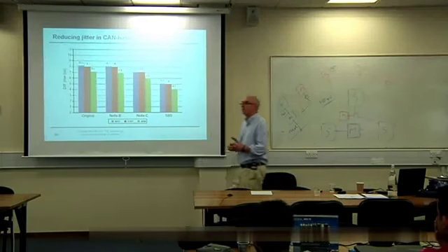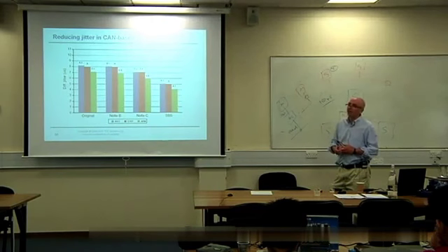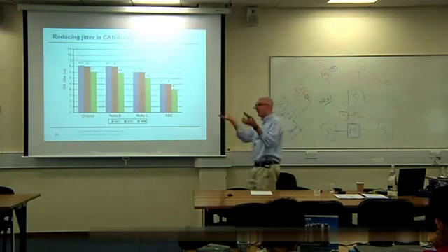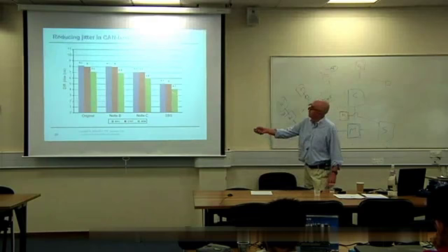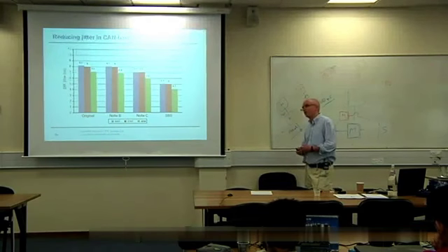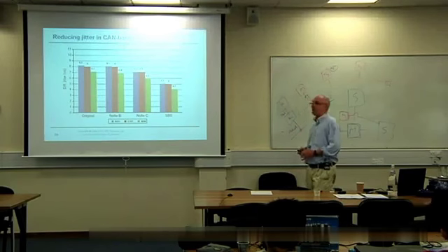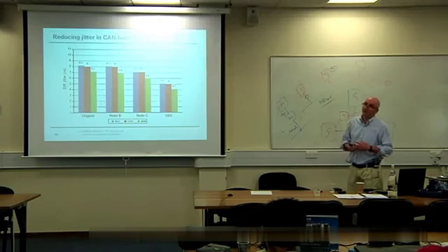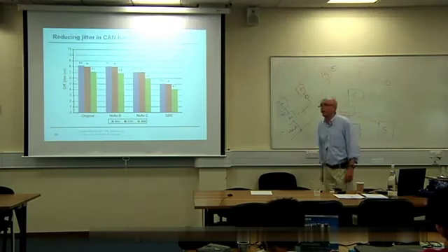The bit stuffing is automatically added by the transmission node and automatically stripped out by the receiving node in CAN. So as far as anything higher up the system is concerned, it's invisible. Why can't you eliminate it completely by artificially doing this? It's because you've only got control of 64 bits in the message. The other bits are set to CRC checks. The other bits are under the control of the CAN hardware, so you can't control those. So that may be enough for you, 5 microseconds of jitter.